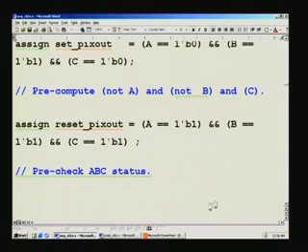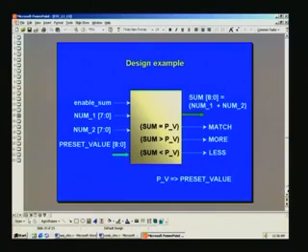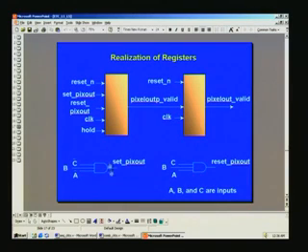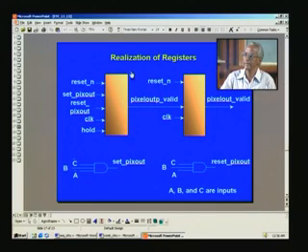And here we have two registers realized in this fashion. When you have just a plain register, which is nothing but a collection of flip flops, say D flip flops, depending upon how many bits you want, and there are reset, set controls, and clock and hold for this, and whatever it stores here we want to use only with the arrival of the next clock edge.